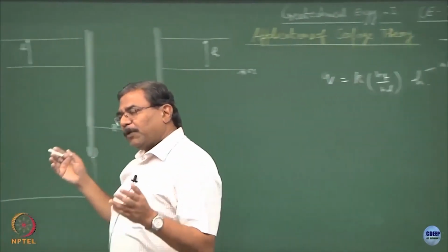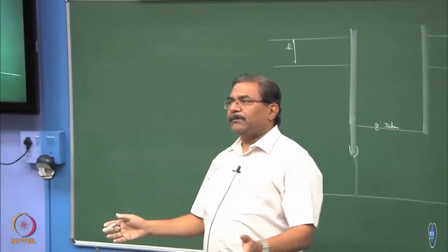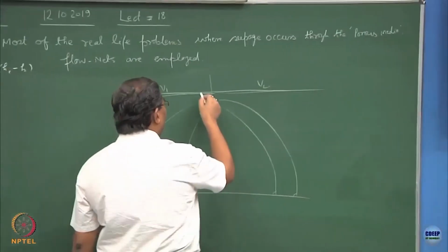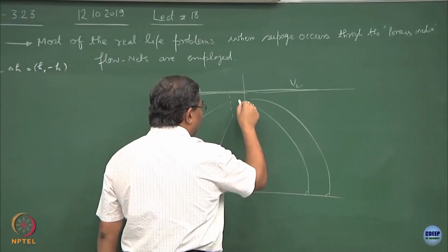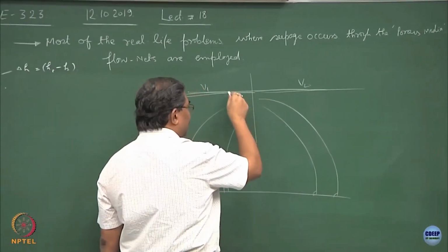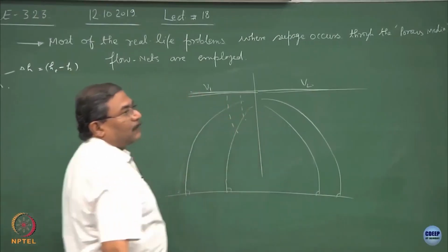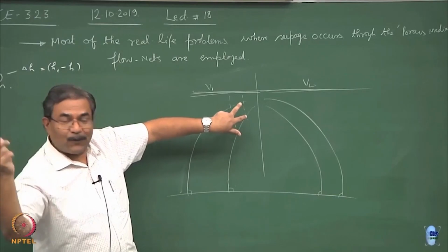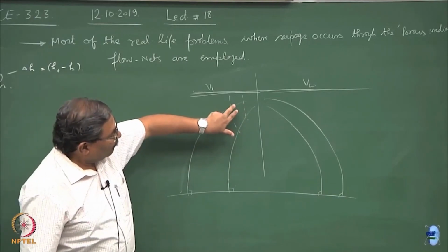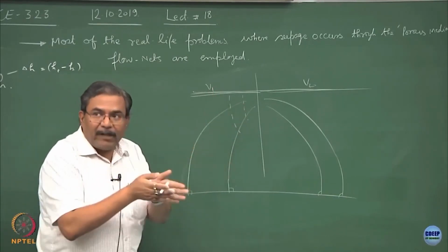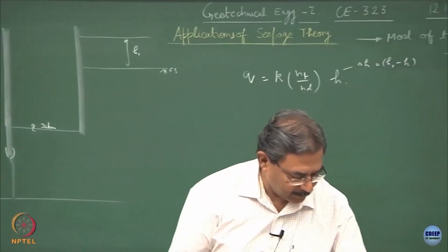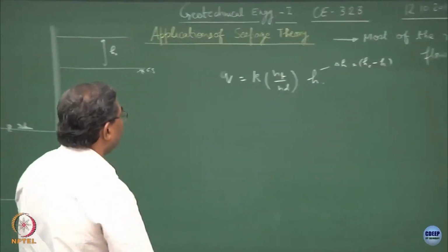Once the equipotential lines have been fixed, you start plotting flow lines, maintaining the geometry of squareness. It depends upon the step for the voltage which you have chosen, because your delta S is equal to delta N. So, if you go for very fine steps, your flow lines will become very fine, with more number of channels.